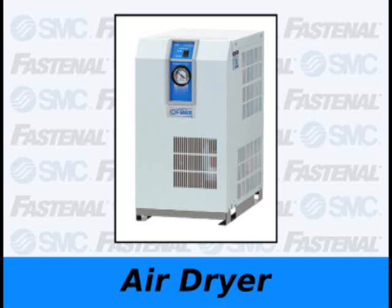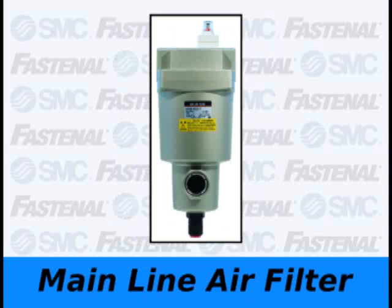A refrigerated air dryer chills the air to try to squeeze out most of the moisture before it can do any damage downstream. Another problem with air compressors is the air comes out with dust and sticky oil. These are bad news for any pneumatic components, so a mainline filter is important.